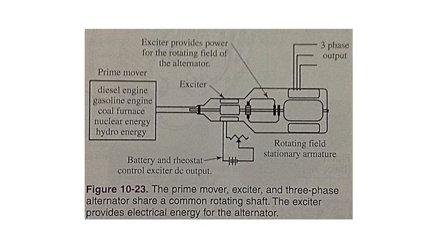In large commercial generators, the magnetic field is rotated and the armature windings are placed in slots in the stationary frame or stator of the generator. This method allows for the generation of large currents in the armature while avoiding sending these currents through moving or sliding rings and brushes. The rotating field is excited through slip rings and brushes by a small DC generator mounted on the same shaft as the rotating magnetic field. This small DC generator is called an exciter. The DC voltage is needed for the magnetic field.